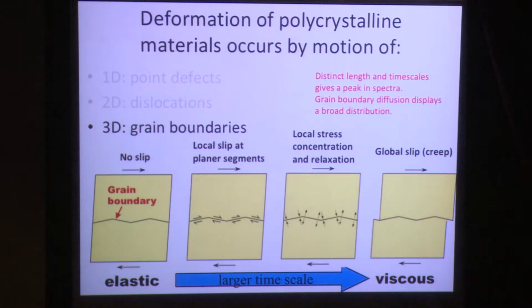They made these very pure samples. They were very careful in fabricating so that they didn't put in any significant number of dislocations. So they were really isolating on a very uniform grain size, this one mechanism, and they still saw a wide distribution in the time scale. So they attribute this to this grain boundary process in response to a stress concentration that diminishes over time. So the more it happens, the more it diminishes. So this diminishing potential creates this broad distribution.